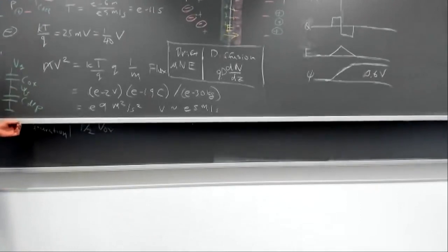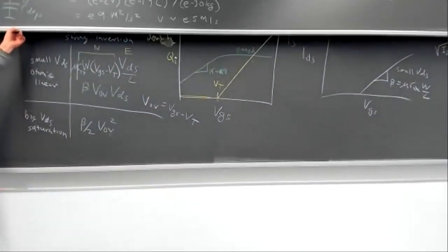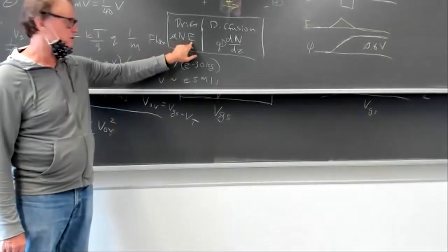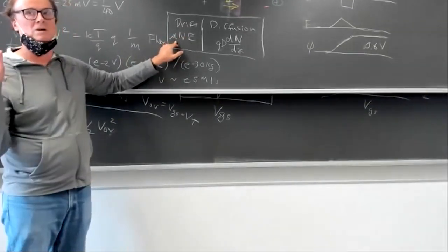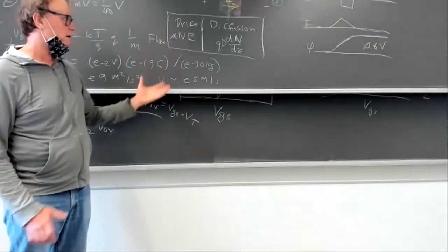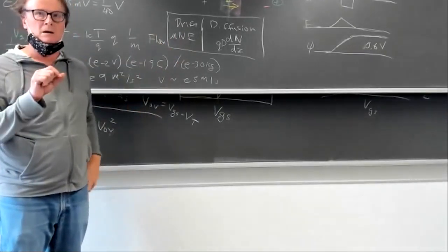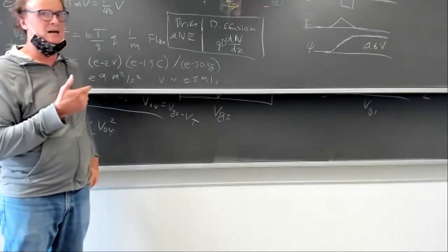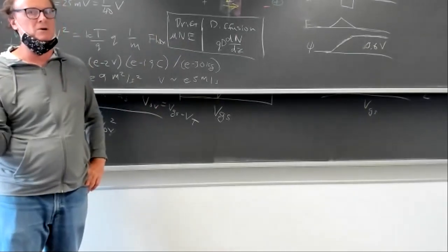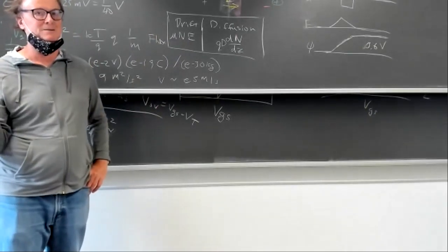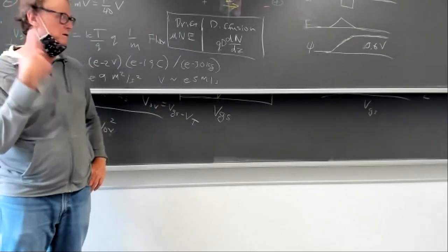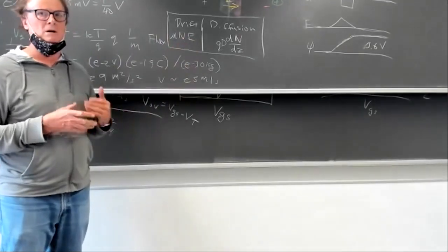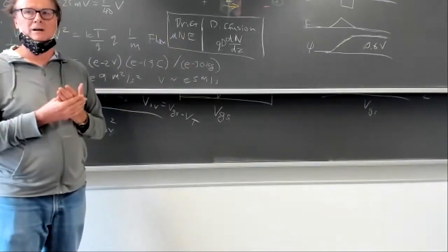Yeah, in reality, the drift current, I've written it like this, that the drift current is proportional to this electric field and a constant mobility. It's not true. For a very large electric field, it's not linear anymore because the carriers get accelerated a lot between collisions, and eventually there's so-called saturation velocity. No matter how big electric field you put on, it doesn't go faster, right? And actually, that's true for a lot of digital transistors now. The current is not proportional to electric field anymore. It just becomes constant with electric field.